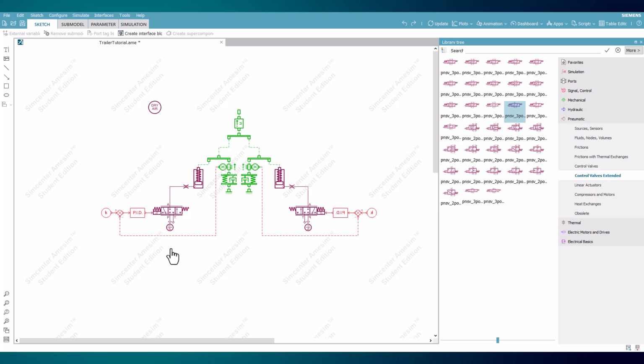Each of these positions will be determined by the current the controller sends, making it so the system will operate where the valve increases the piston's pressure when the suspension is compressed, and closes the piston chamber off when that pressure value has been met, and with that, submodels can be assigned.